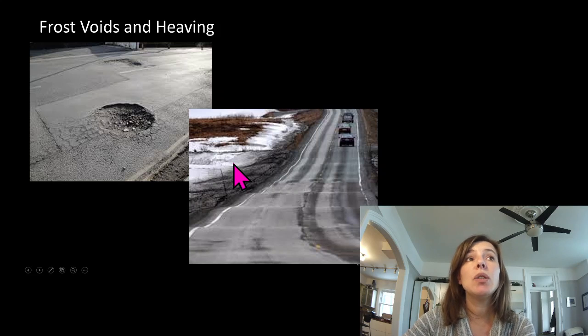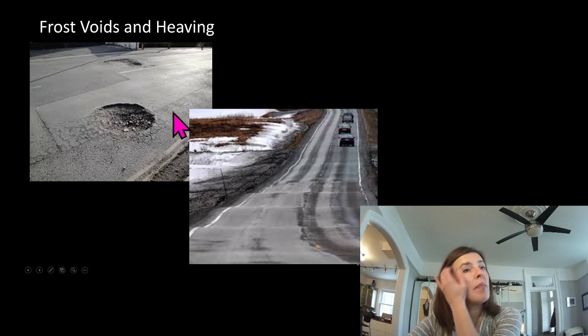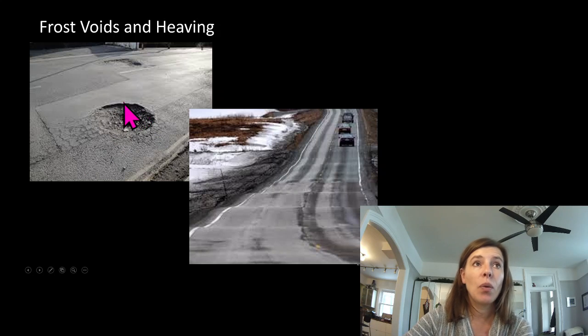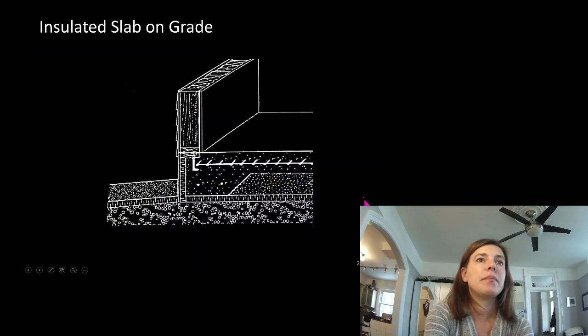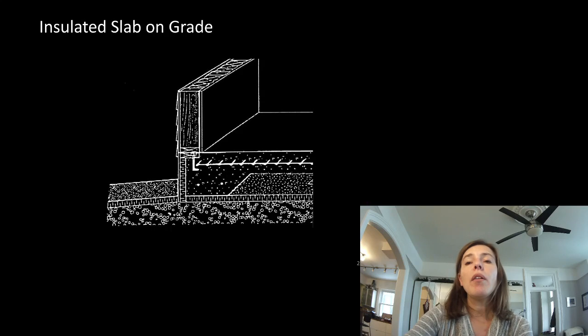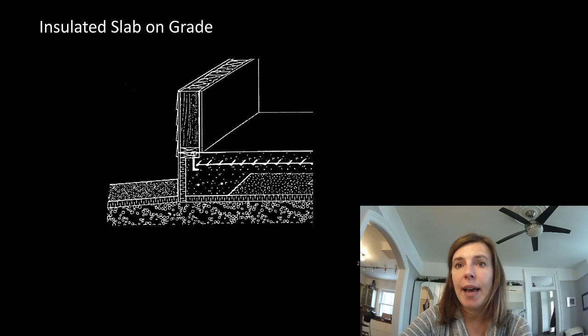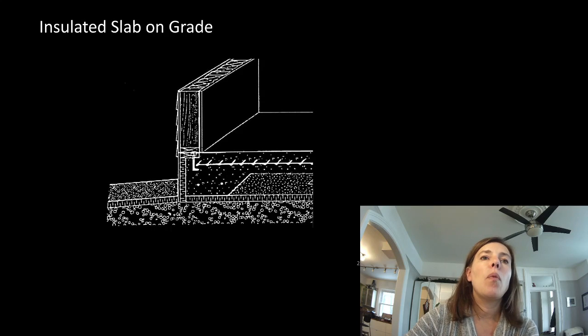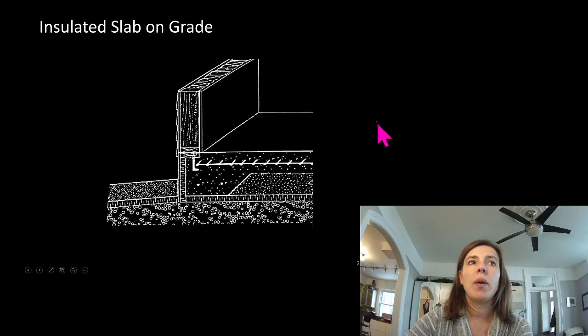So why do we worry about frost? So here you can see where we can have the soil leave the zone and we end up with a void, or it can freeze and lift up the soil. So what are alternatives to going down 4 feet? Sometimes on sites that's a really hard thing to do. What we really are worried about is protecting our foundation, but also our slab.